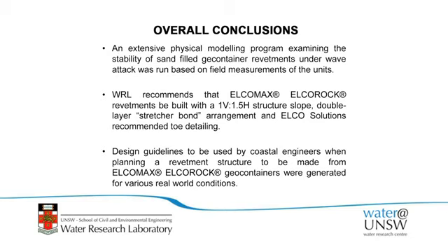We've published some design guidelines based on this output. It's been put in the last Australasian Coasts and Ports conference as a paper that summarises all these design conditions for real world conditions. We tried to come up with quite practical guidelines where we simply put a wave height at the structure and wave period as the main things to think about, rather than some fairly esoteric inputs such as water velocity at the still water level.